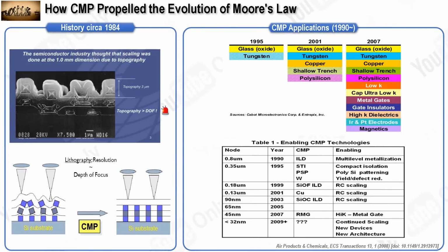Copper metallization technology in the back end of line, known as dual damascene, replaced aluminum interconnects, providing superior conductivity and manufacturability. The diversity of materials polished in CMOS process flows has expanded steadily, reflecting CMP's growing importance. Initially, the planarity requirement was 50 nanometers, but now the industry strives for absolute planarity, 0 nanometers, with a zero defect standard. This pursuit of perfection underscores CMP's critical role in achieving the high precision and quality needed in modern semiconductor devices.